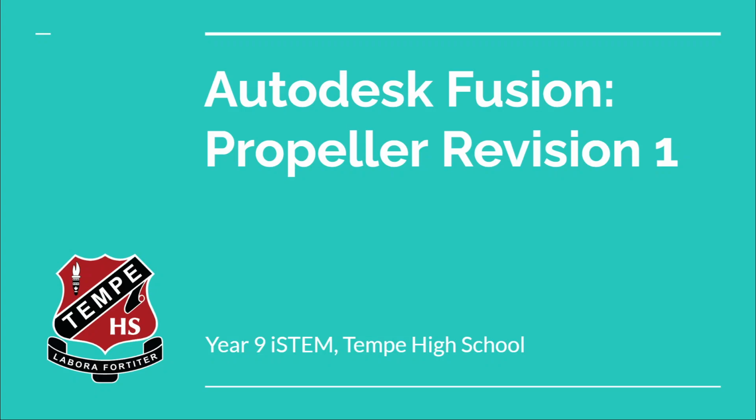Okay, welcome everyone. Today we're going to go through our propeller design revision 1. What we did last time was the trim style propeller, where we made a curvature and made two shapes as a surface and used a cookie cutter method, the trim method, to make that curvature, and then we repeated that as well. Instead of using surfaces this time, we're going to be using an aerofoil sketch. We're going to be setting up planes and the core function will be a loft function, what they call a loft, okay?